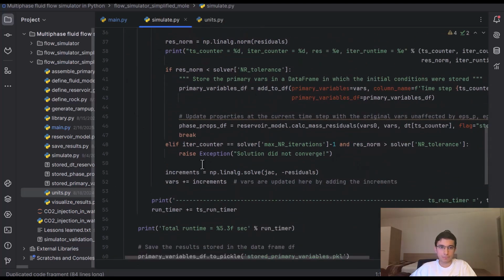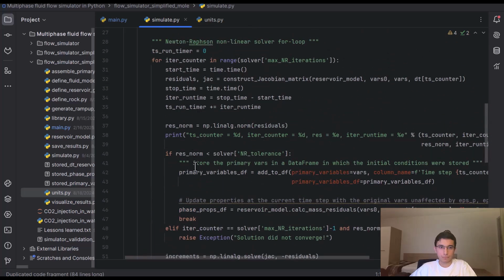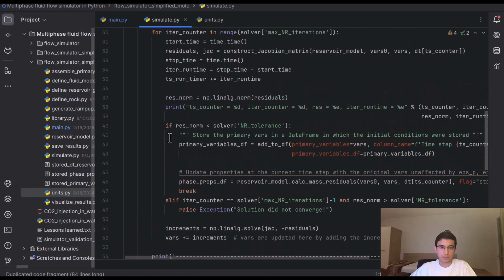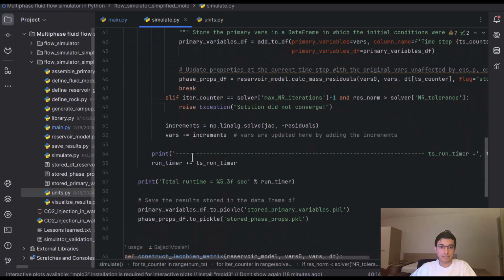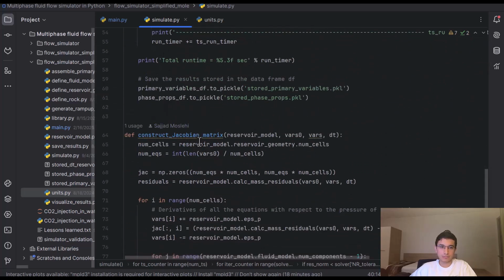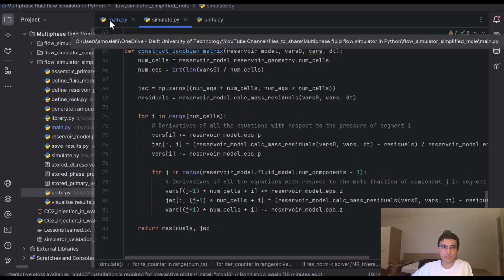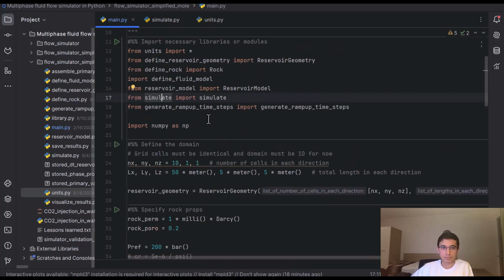and we have a number of for blocks and if blocks to see. In this if block, for example, checks if the solver has converged or not. And yeah, in this script, we just try to solve the governing equations using the Newton-Raphson method, as I mentioned before. And this script is used to create time steps in an increasing way.